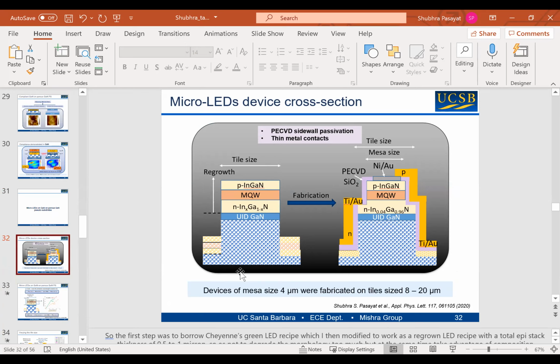Okay, thank you. So I see a few questions in the chat. Let me start addressing those. Vincent asks, how thick was your porous layer again? The total thickness of the porous layer is 800 nanometers. And do you think with proper optimization, a porous device could survive a flip chip bond? I think with proper optimization, you can pretty much do anything. So yeah, that is possible.